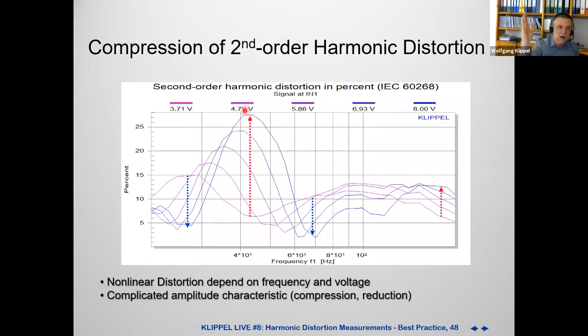So the coil is moved out of the gap, or you are centering the coil quite nicely automatically, and then you get less distortion. So if your customer is very keen on this frequency range, and you can convince him to provide a higher voltage to the loudspeaker, you get a better speaker. Then of course that is quite interesting. So you are using the self-centering feature of the natural loudspeaker. But here it becomes unstable. Here you get more distortion, that's bad. So measure at different voltages, you get interesting results.